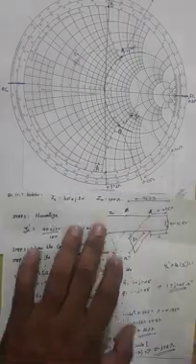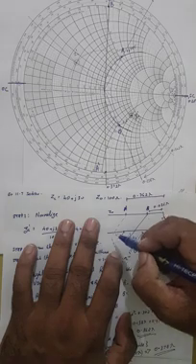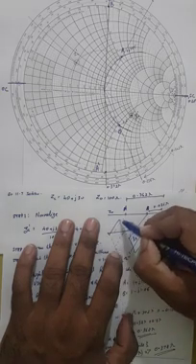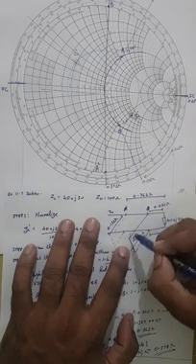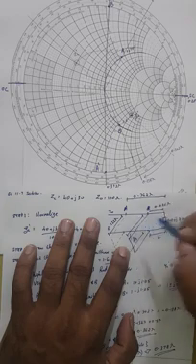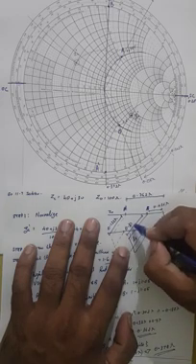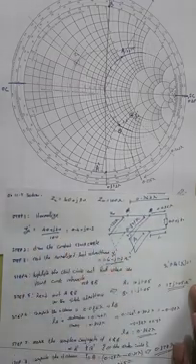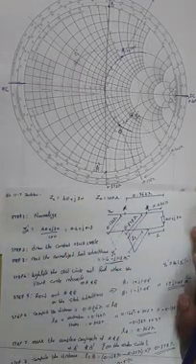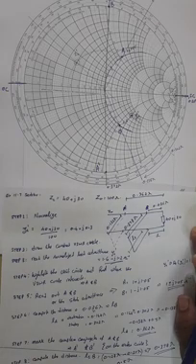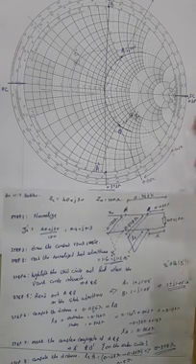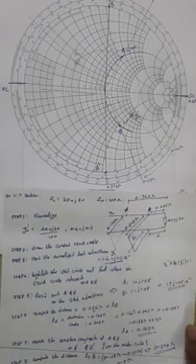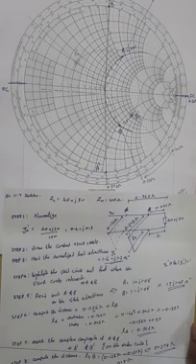So if required, I can compute the length at A as well. Over here I will have 0.122 lambda, and over here I will have 0.378 lambda. So this is going to be my solution to compute double stub if required, single stub if required, using a Smith chart without using the analytical method. More later. Thank you.